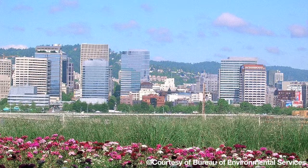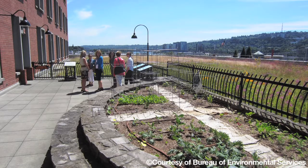The footprint of the vegetated portion of the green roof is approximately 11,900 square feet. The catchment is 15,420 square feet, including the planted area, stone terrace, and pavers along the perimeter. Overflow drains to internal downspouts, which are connected to the combined sewer system.